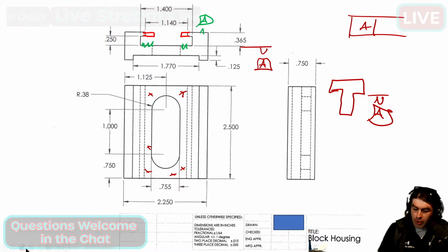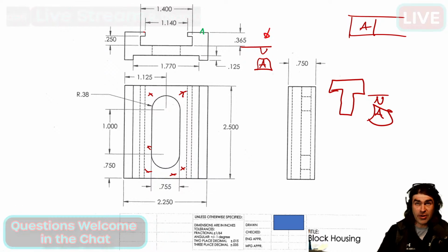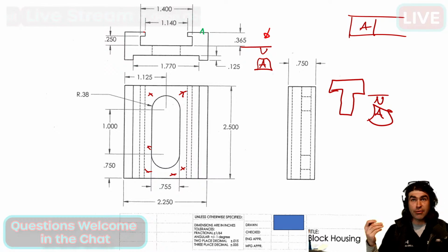Okay, check it out. So after all of that, what decision am I going to make here? I'm going to stick with this as our primary datum. I can get to it with a CMM probe. I can live with it, right? It's a very functional feature. Secondary datum, we're probably going to need 3 in this case. So this is going to take away 3 degrees of freedom.